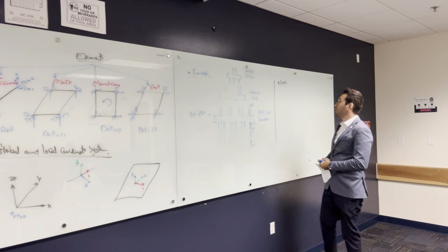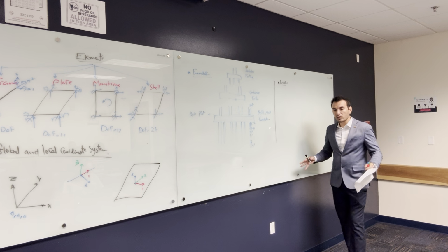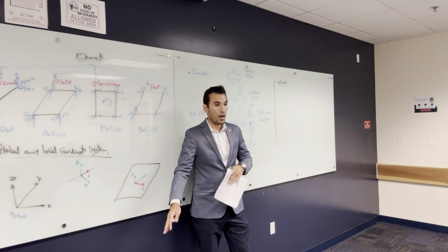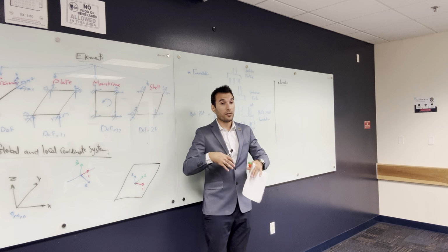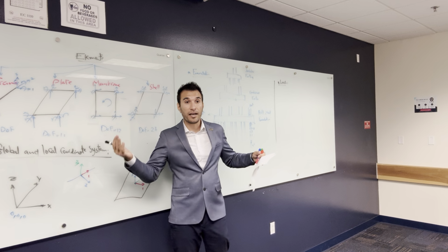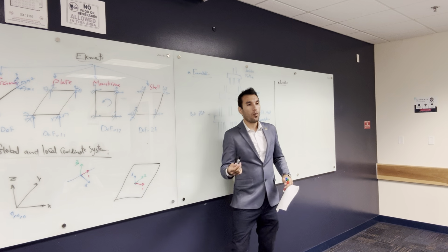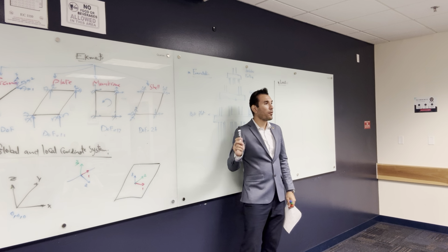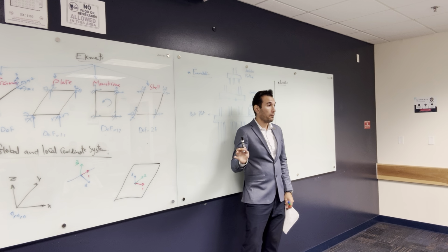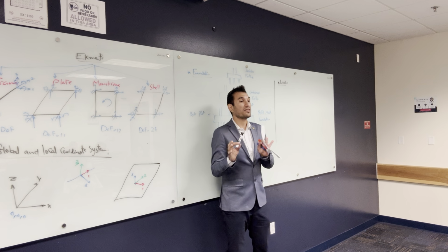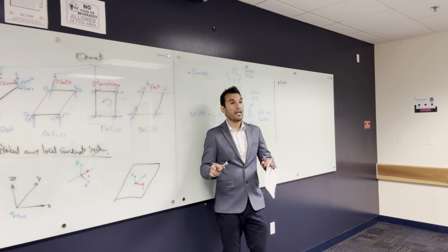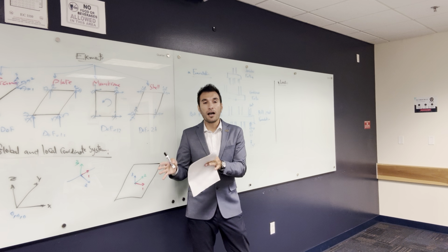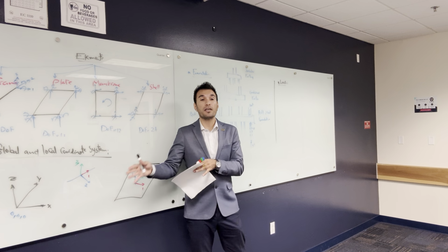Okay. All right, so the thing is, all these loads come together on the structure. Like this structure right now, it's under its own weight, under our live load, and maybe under other loads that can happen randomly, seismic, wind. But the thing is, what is the chance that this structure is going to have the maximum of all these loads at one time? There's no chance. Maybe there is, but it's a low chance. That's why the engineers or the researchers did some statistics so that they can come up with the extreme load events for the structure.